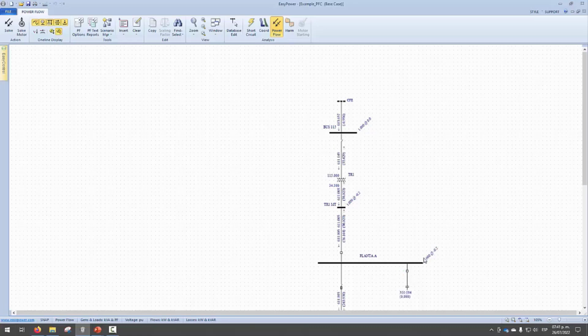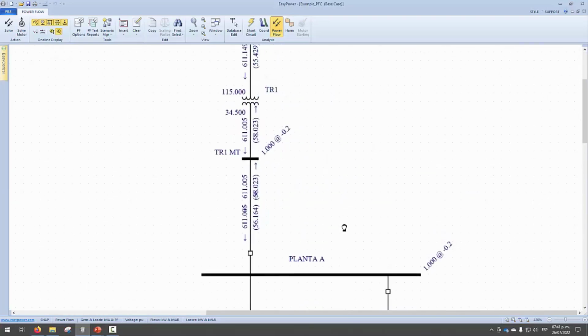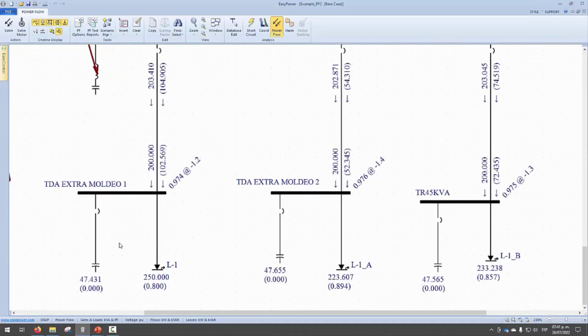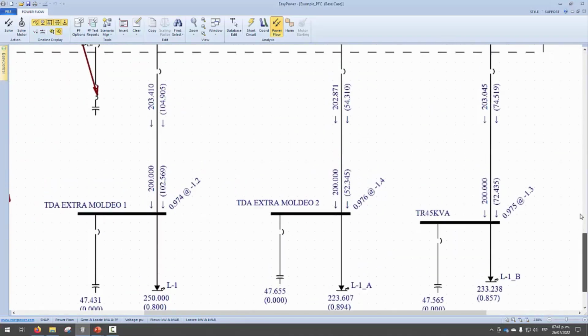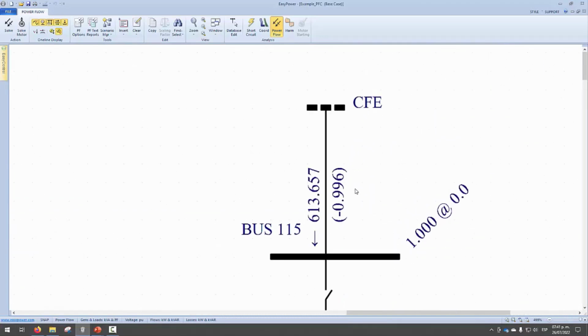Okay, so then I put this bank on the middle voltage side, and it's delivering 300 kVAR along with the banks downstream, right? So then I go up to the utility, and I went a little on the capacitive side. I went a little overboard, but I think that would be okay. That would be acceptable, and I'm very, very close to unity. So the plant manager is very happy.